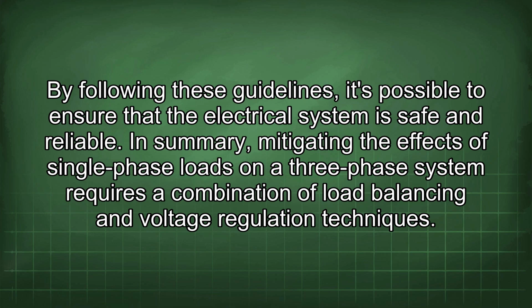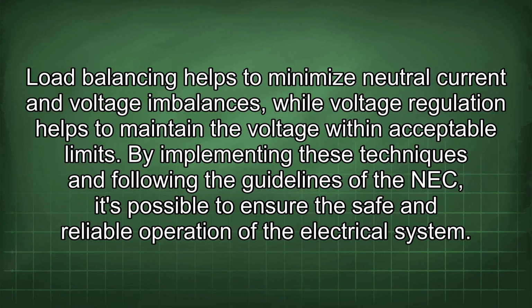In summary, mitigating the effects of single-phase loads on a three-phase system requires a combination of load balancing and voltage regulation techniques. Load balancing helps to minimize neutral current and voltage imbalances, while voltage regulation helps to maintain the voltage within acceptable limits. By implementing these techniques and following the guidelines of the NEC, it's possible to ensure the safe and reliable operation of the electrical system.